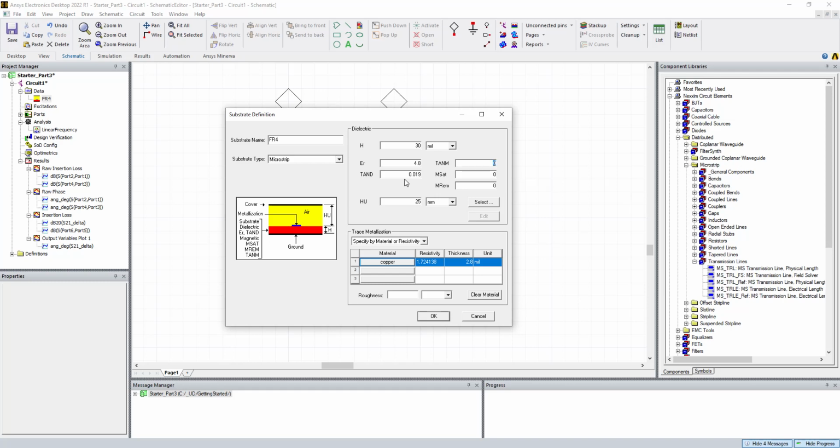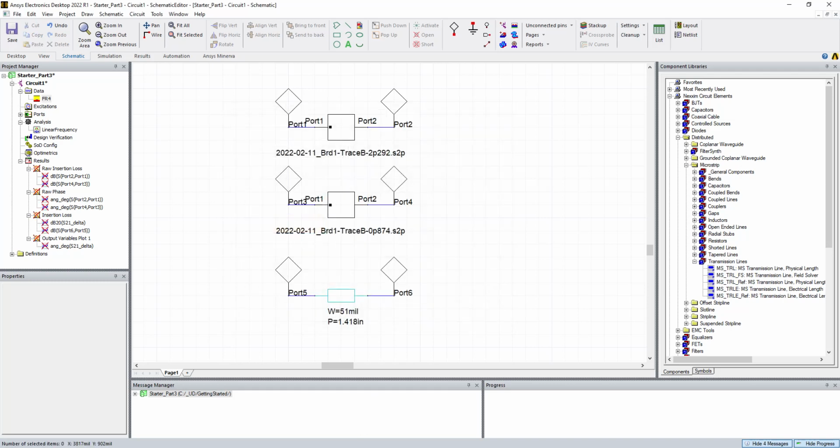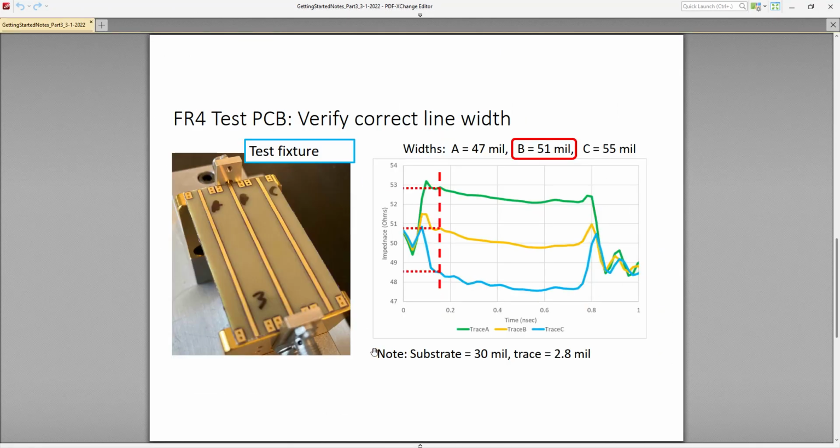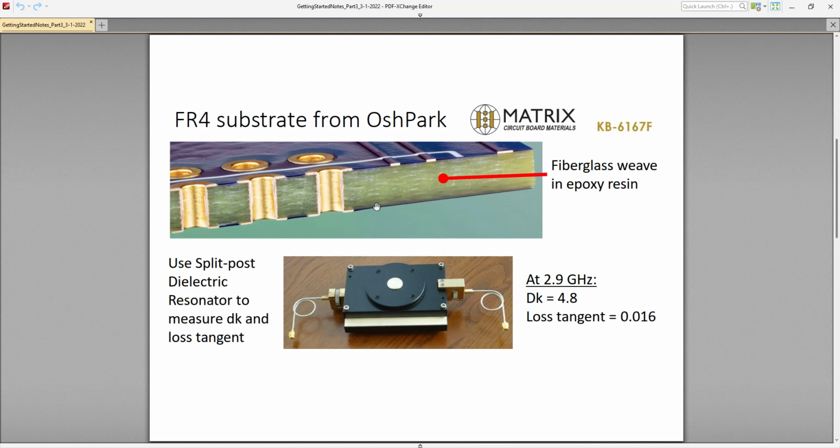So it's very possible. If you notice from the cross section of the circuit board, okay, let me just show you that real quick. Let's go back to here. Up, come on. There we go. Okay. See how this has got a lot of fiberglass and resin? It's very possible that the way this measures it, which is the electric field in the plane of the substrate, is not going to give you exactly the loss tangent equivalent that would be for a microstrip where the electric field is in this direction. So just something to keep in mind, a small subtle detail.